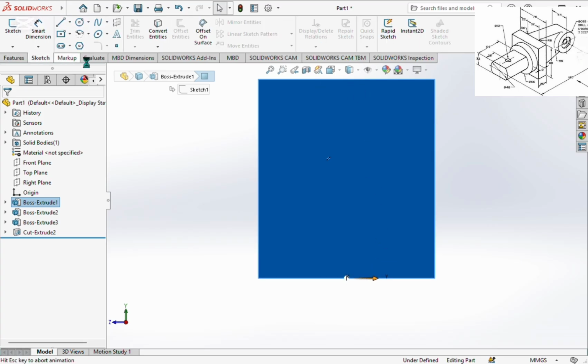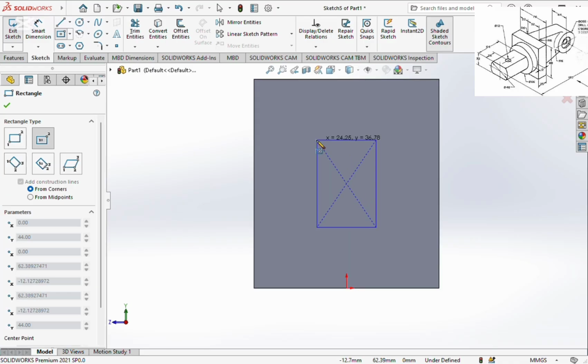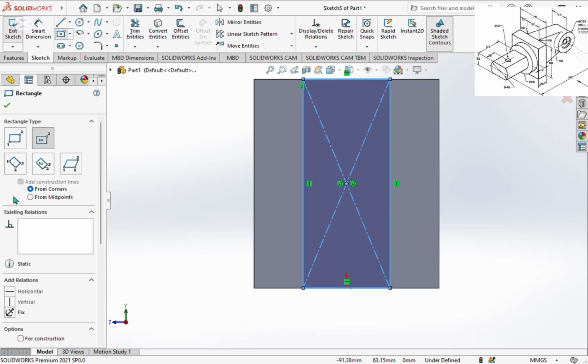Now I'm going to use my rectangle command. Now with my rectangle command, I think I use, is it center? Yeah, center rectangle. So I started from the center so that I can get the center of this face. You can see what I did there. Center rectangle. So I'll need it from up there. I will firstly get the rectangle first. Now, what I need now, I need that rectangle. First of all, I will change the dimension of the rectangle part there.